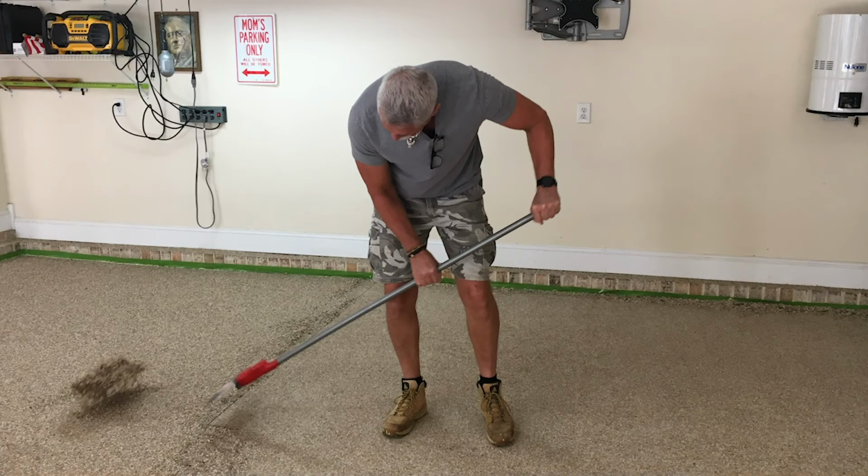Now, fast is okay, but the problem with fast is if it goes so fast that I can't get it applied to the concrete fast enough based on the heat, meaning it's going to start to cure or start to react, I should say, before it's able to do that absorption into the surface, it might not absorb as deeply as it needs to. So the failure, again, is not a coating failure. It's an application failure because the coating actually started to react and thicken before it hit the surface and was able to absorb in.